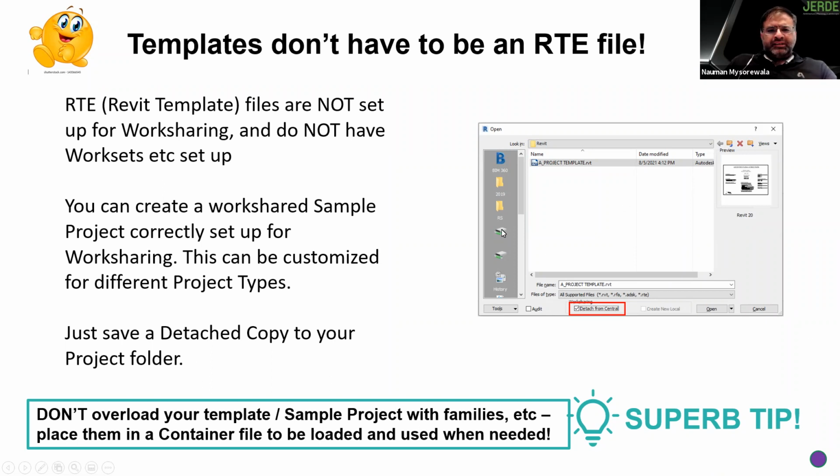But the one thing that in any case you should do is not overload your templates, be it with this trick or just the RTE file, with families. Just keep them in a container file, keep details in a container file or in libraries, then people can load them very easily.